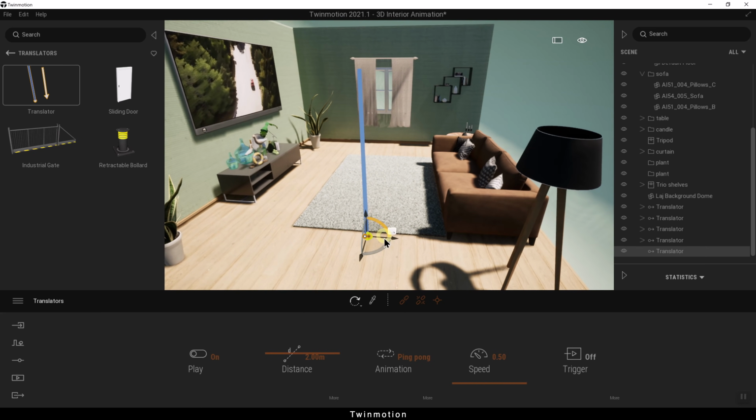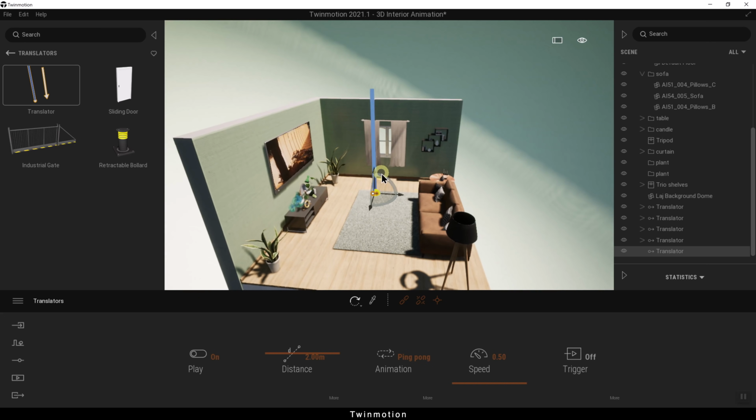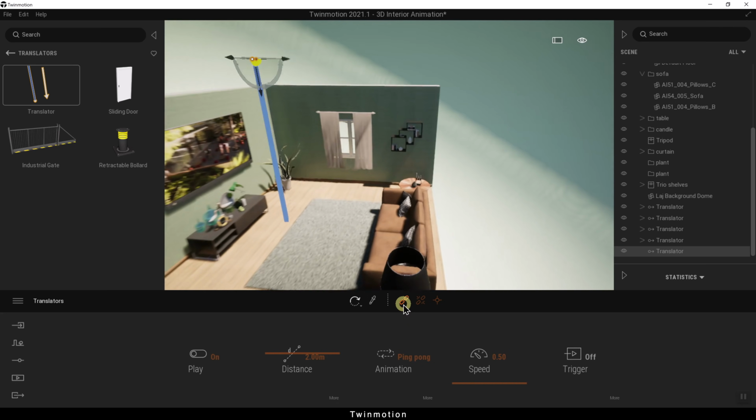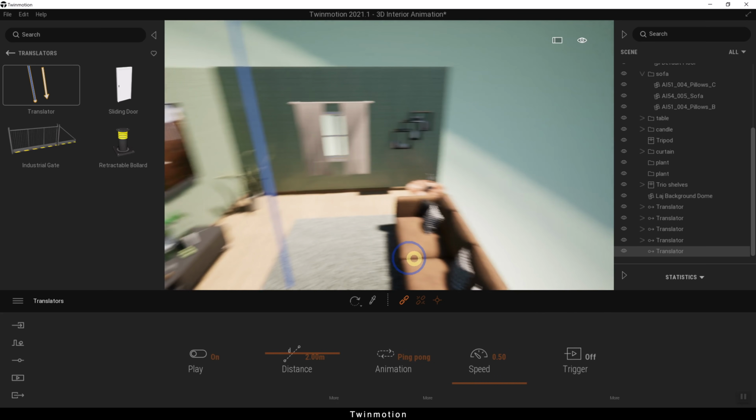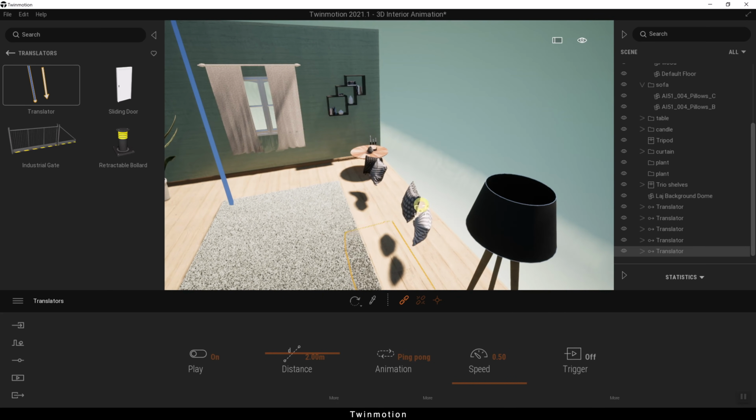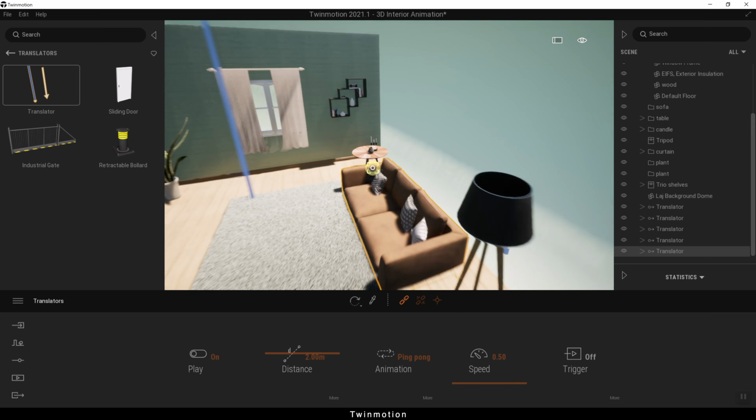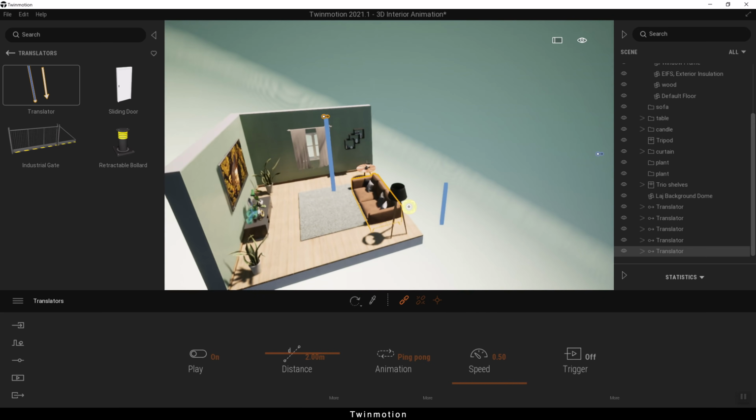It moves the objects, and we want our sofa to come from above. We have to turn this exactly 180 degrees because it goes up from the bottom like this, but we want it to come down from the top. So we rotate it 180 degrees, either by writing the number and pressing enter, or by rotating it manually, whichever you are comfortable with.